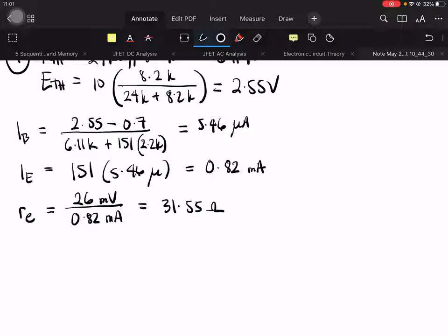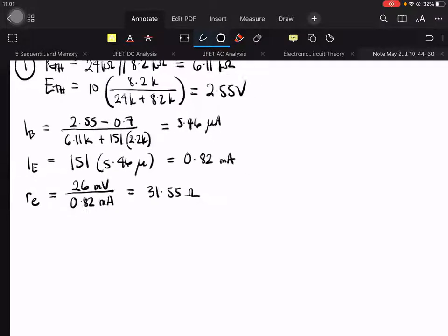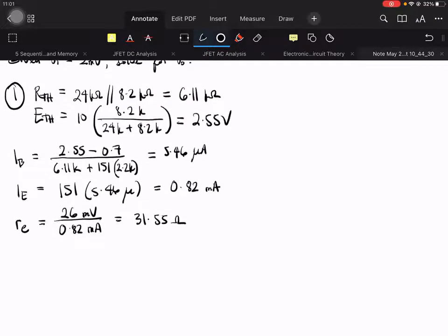So, yan na, no? Next. Okay, impedances na. So, BJT summary table for AC. Voltage divider. So, ZI is R1 parallel R2 parallel beta re.